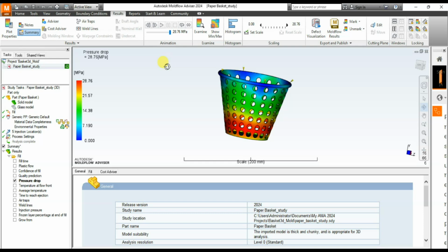In order to create a better confidence of fill, the maximum injection pressure should be increased. Another important thing that we should take note of is moving polymer injection locations closer to the problem area, or adding additional injection points to improve the likelihood of all sections of the part filling.